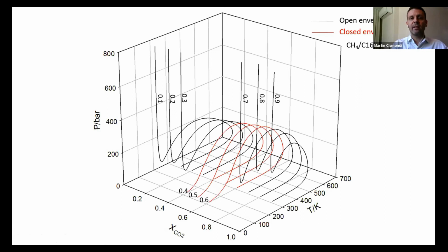You see, the point is that the standard phase envelope algorithm will get these ones because they are connected to the vapor liquid part, but usually they don't get the other ones because they are not connected to the vapor liquid part. That can be of practical interest or not, depending on the case.